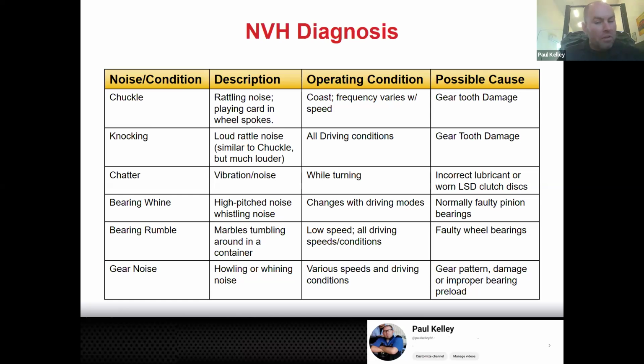Kind of decent on overall differential stuff, because pretty much that's where we need to be. Then, of course, if the fluid was low, you could always say, hey, when the fluid goes low, it ruins that front pinion bearing. That's the one that's the furthest up, so the fluid gets starved for that one first. You can consider some of these different factors as well.